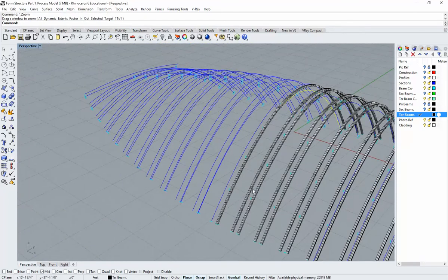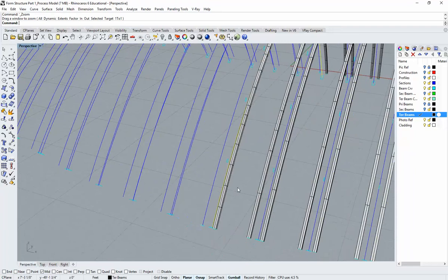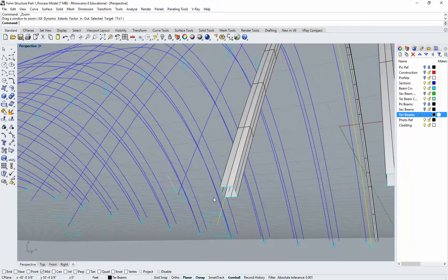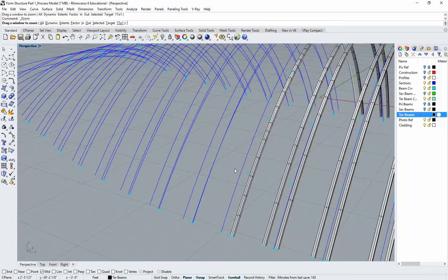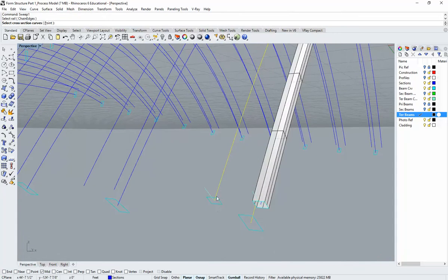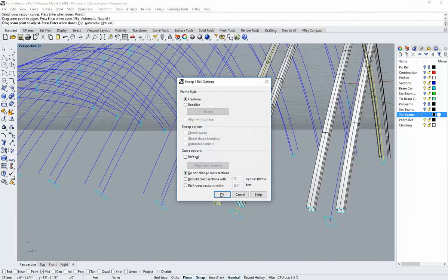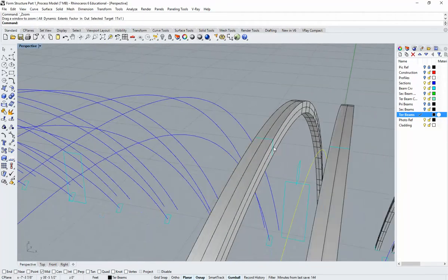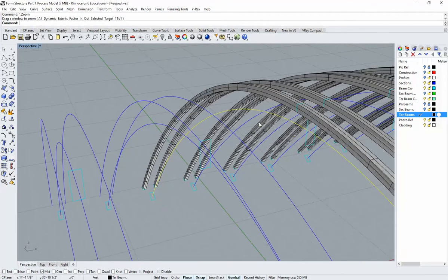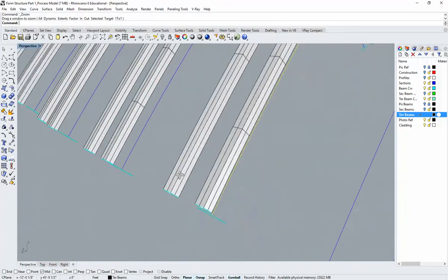Hey guys, just clicking back in just to show you also that, as it turns out, you only really need the one profile. You don't even need to mirror it or have them up at the top. That could actually speed you up a little bit. Turns out the sweep is a little more accurate than I thought. So you can just select the rail and one of the outer edges, like we do here, and it actually sweeps across nice and evenly right through the curve here without even needing to force it. So that's nice. So anyway, that's a little bit faster.